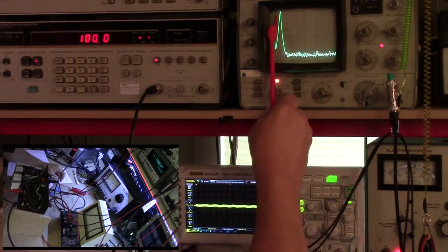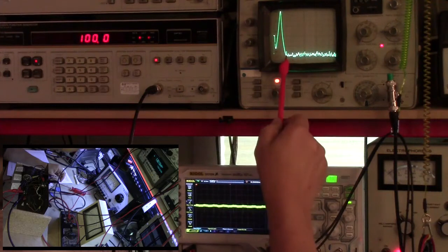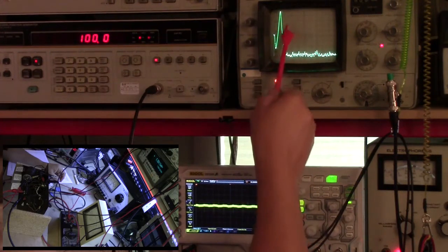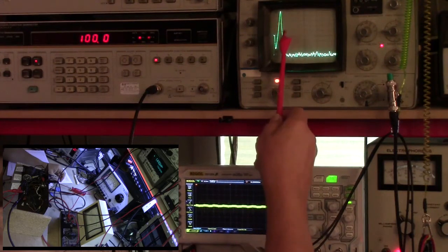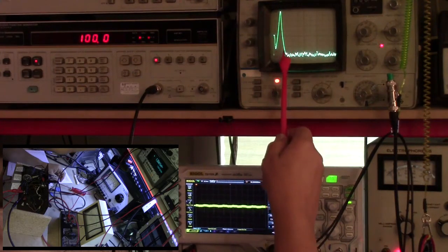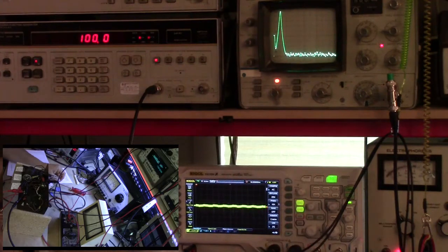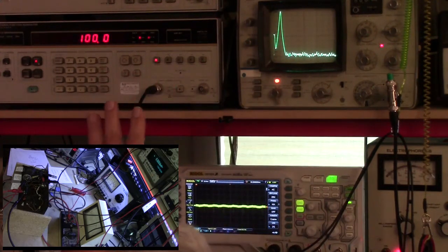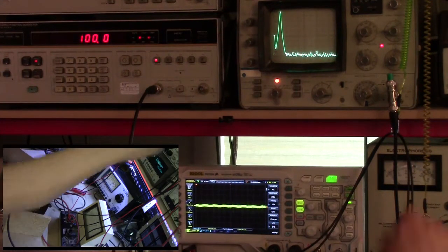This is a 1 kilohertz peak, and then the second peak is going to be right here, and you can't really see it, but this is 10 dB per division, so we're 10, 20, 30, 40, 50, 60, 70, 80, about 85 dB down. So spectrally, this frequency generator is actually working really well in terms of putting out only the fundamental. And it is a synthesized frequency generator, so you expect that kind of performance from this.